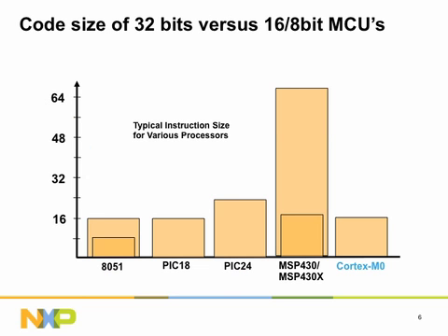An 8-bit architecture does not mean that the instruction length will be 8 bits, nor does a 16-bit architecture mean 16-bit instructions. This bar chart shows graphically how instruction length can vary with the processor architecture. For many 8-bit microcontrollers, instruction widths can be 16-bit or larger.